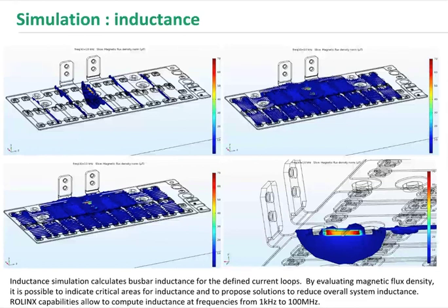One example of how we can improve is, if you remember one of the slides before, we talked about the Z-bend, the dishing and the bushing. My colleague mentioned that with a Z-bend we had an inductance of around 32 nanohenries. By changing to the dishing, so basically the preforming of the material, we could reduce it to around 11 nanohenries.